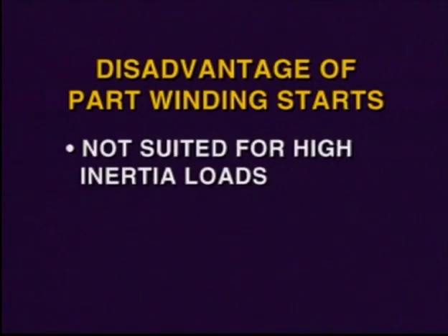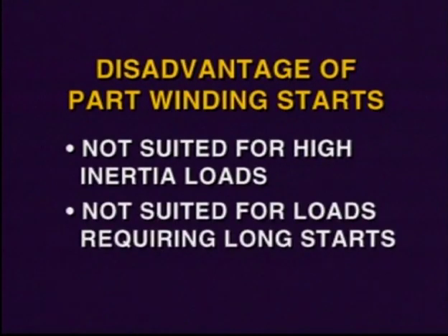One disadvantage of this method is that it is not suited for high inertial loads or loads requiring a long starting period. In fact, if this motor start is longer than 5 seconds, it will overheat. The standard time for the acceleration step set by the timer is between 1 and 1.5 seconds.